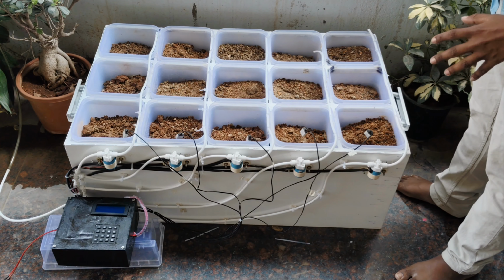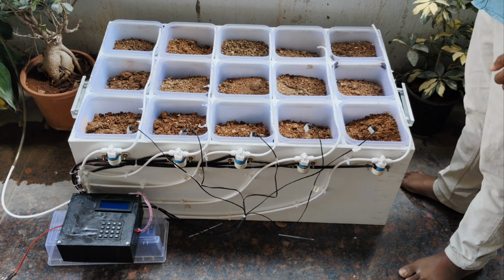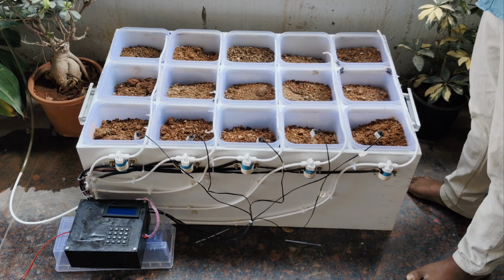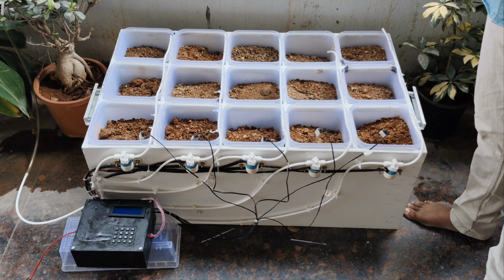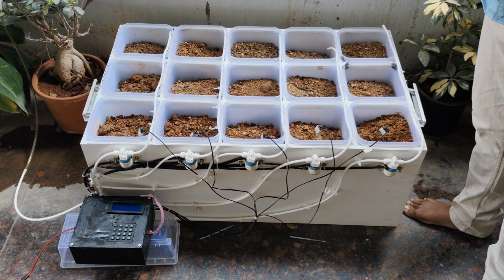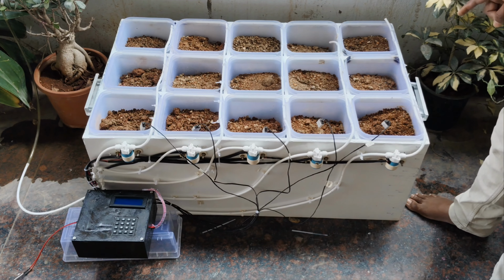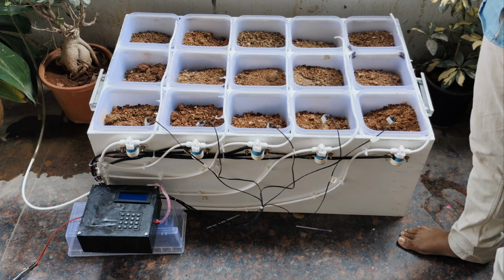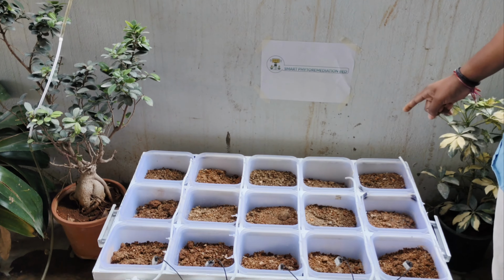The entire system is monitored and controlled by an STM32 controller. For the user interface, we have given a 20 by 4 LCD display and a 4 by 4 keypad. The complete data will be stored in an Excel sheet with date and time reference in an SD card. We are using an SD card reader for it. The system waters the plants completely by gravity. We are using a tank, keeping a head, so that the system waters the plants only through gravity.